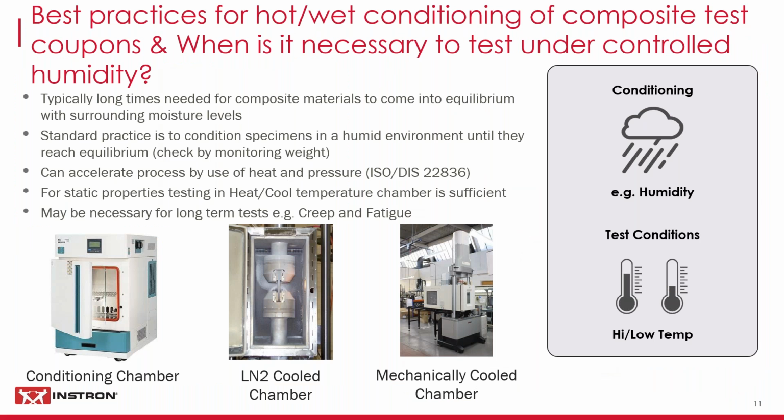So, best practices for hot wet conditioning of composite coupons. When is it necessary to test under controlled humidity? Well, typically when you're conditioning composite materials in humid environments, it will take a long time, days or weeks, for these materials to come into equilibrium with the surrounding moisture levels. It's work that's typically done in a conditioning chamber. You can see a typical chamber in the slide.